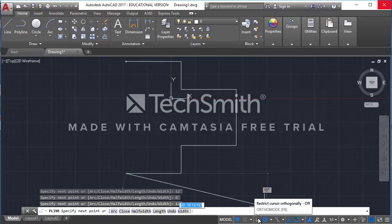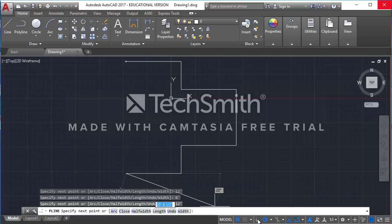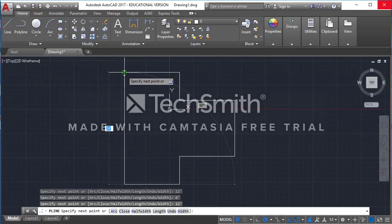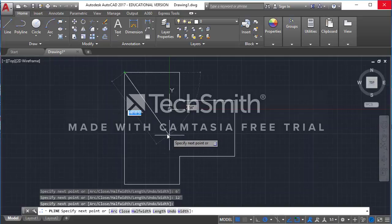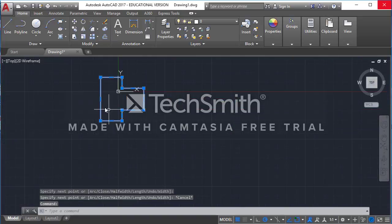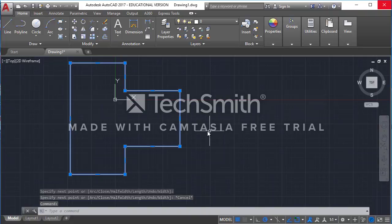Well, if we go down to our bottom ribbon over here, let's see, where are my snaps? I will actually come back to this in a second because this is a little different from my work computer. As I mentioned, everyone has their own AutoCAD layout. This is a little different from how I work in my office, but notice that when I bring my mouse up to the top, this snaps to that line. So now that I've completed the outer perimeter of my house, I can hit escape, and if I hover my mouse over my line, notice that I have one large line.